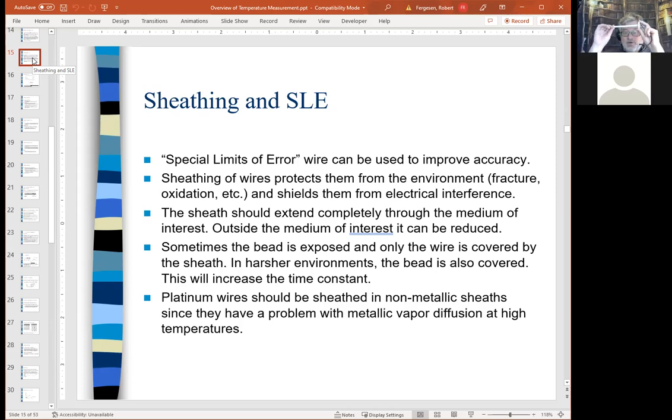So this is designed for extremely high temperatures, 5,000 or 4,000 degrees Fahrenheit, very high temperatures, or anyway, right at the high end of the thermocouple, maybe not quite that hot. And so even if your thermocouple wire can handle the high heat, it probably won't be rated that high when you purchase it, depending on the sheathing. So the sheathing is very, very important.